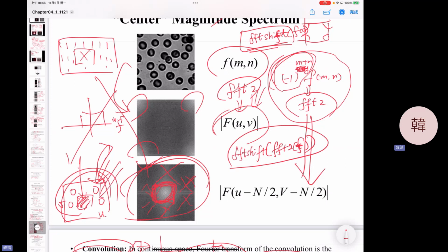If you only keep the low frequency components in your magnitude spectrum, what does it mean? You are applying a low pass, smoothing filter, because you discarded all the edge information, which is in the high frequency components.